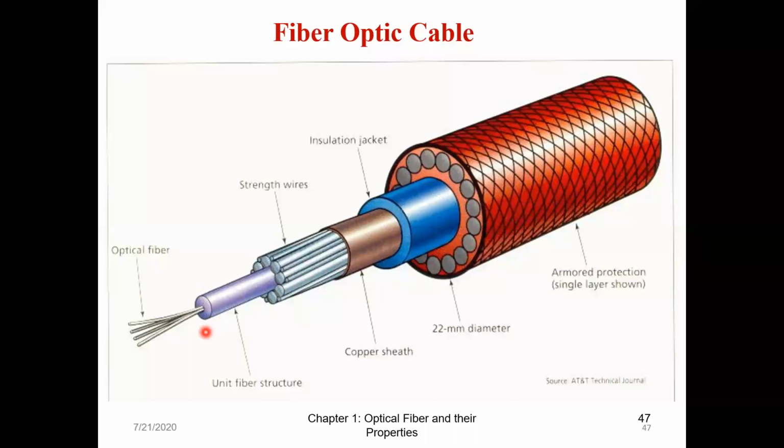diagrams. Right now I'm just telling you that we have something called a loose filled buffer jacket. Loose means it is not tight, it is not immediately touching the fiber, and we fill this vacant area inside the buffer with a petroleum jelly kind of material. So that's why it is a loose filled buffer jacket.